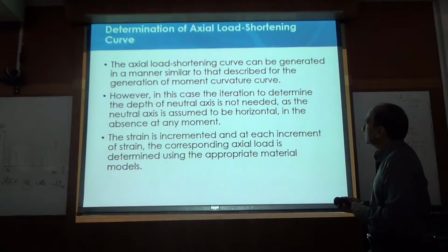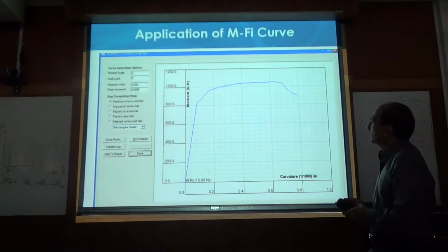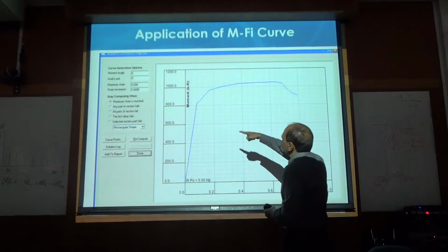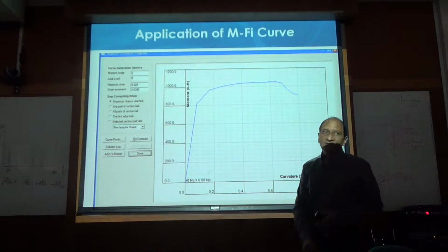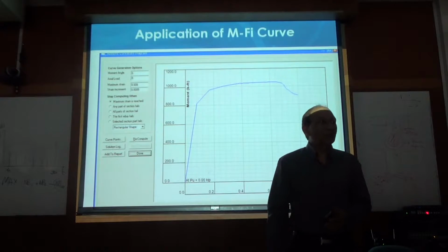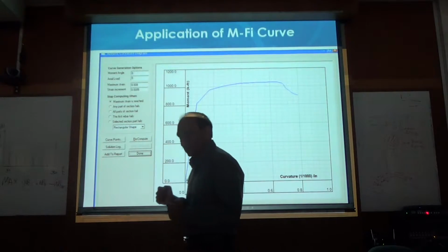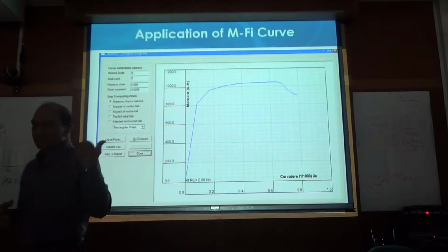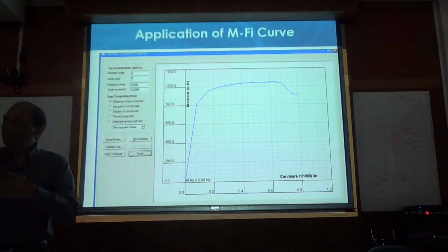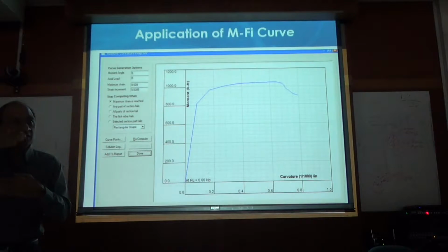Let's look at the stress application now. So typically, a moment curvature curve should look like this in reality, where we have combinations of failure. In fact, there is no single rebar in the column. Let's say this is a column. There are many reinforcements. So each yielding of each rebar will create a certain point or certain change in the curvature.